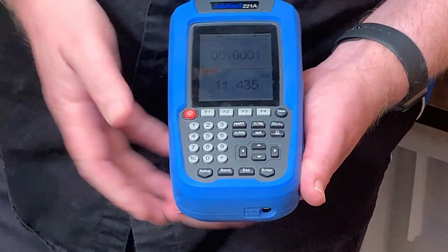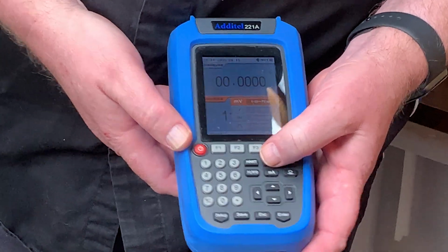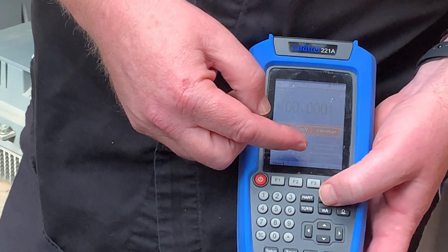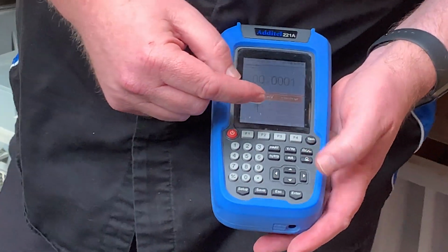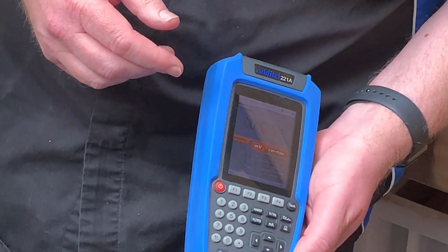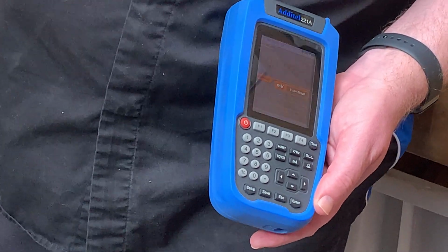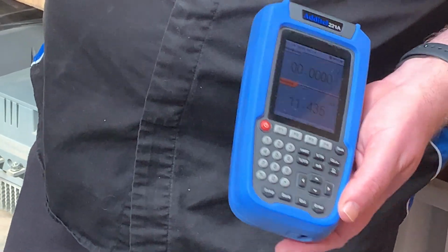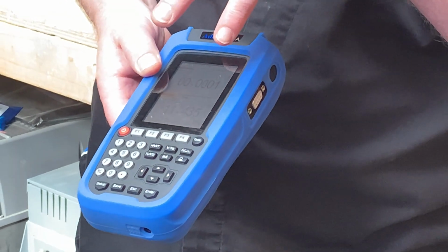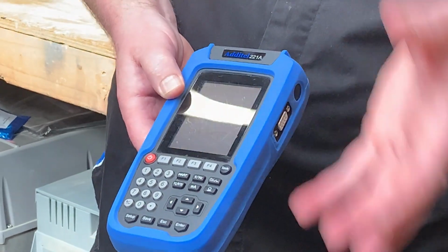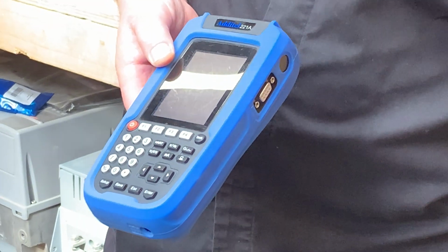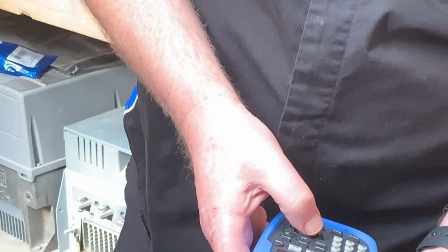So source measure. If we go to volts, now on this one you've got some choices. You've got millivolts, volts, frequency, pulse counts, and you can source and simulate. So imagine, for example, with pulse counts, if you've got one of those flow meters that has a pulse output, 1 pulse per litre or 20 pulses per minute or whatever it is, you could simulate, if you know what the flow meter should be. So you go to the manufacturer and say, hey, that flow meter you supplied me with, the pulse output, what is the rate of pulse? So you can simulate precisely that.